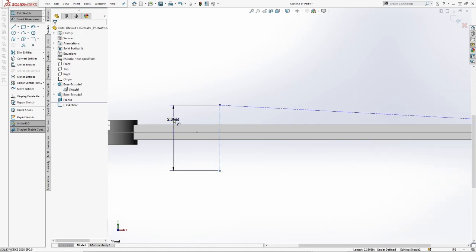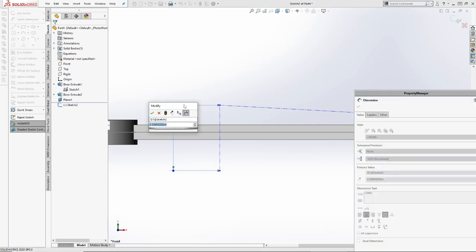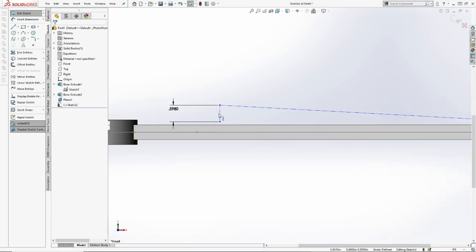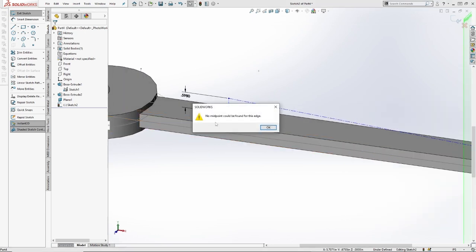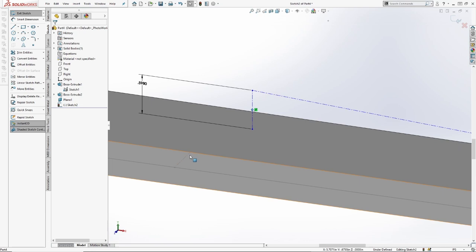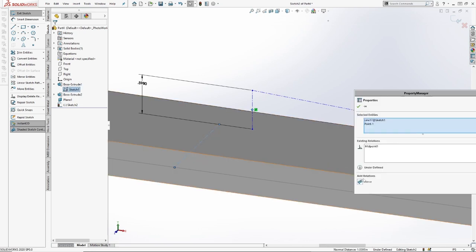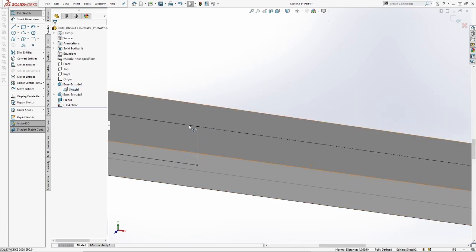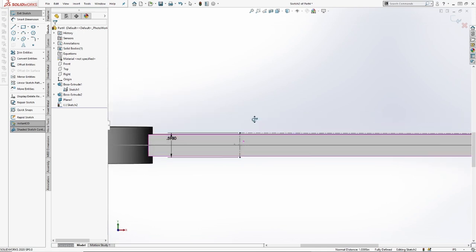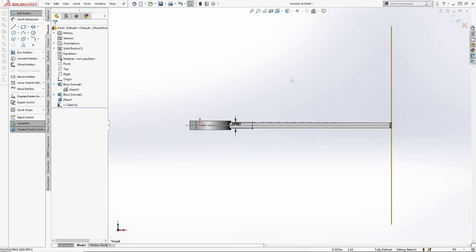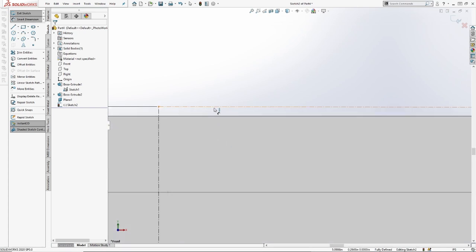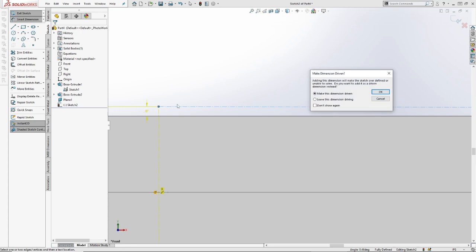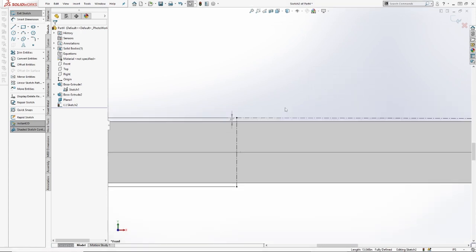Here's our N1 value, which is 598. I'm going to put the midpoint of that piercing that line. So that sets up where that dimension's taken. I'm going to throw in an angle here. This is going to be a calculated draft.